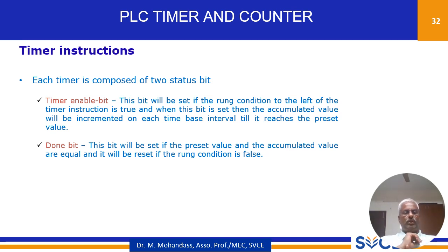So there will be a predefined delay value in terms of seconds or microseconds, and once the timer input is energized, it starts to count from 0 until that counting value reaches the predefined value. Until then, the output of the timer is in off condition.